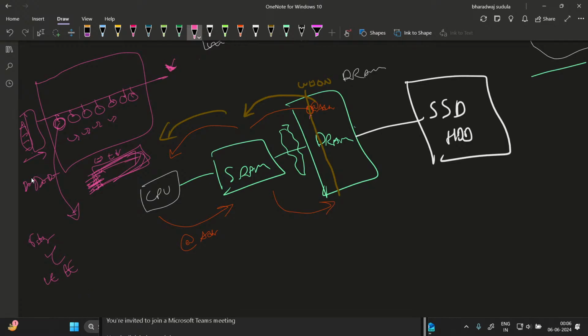Whatever you have studied in Rabaey's lectures will be helpful in this decoding part. So row decoding takes a lot more time than column decoding and shifting to the adjacent column. The column side has only transmission gates, so it's easy to turn off one gate and turn on the adjacent gate.